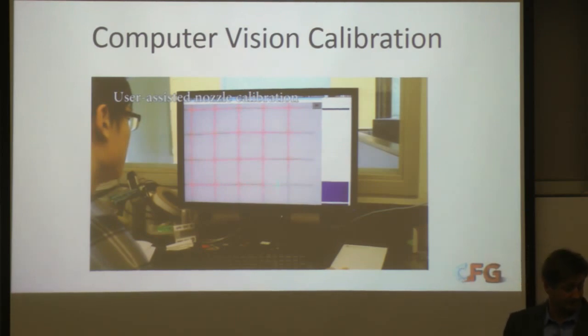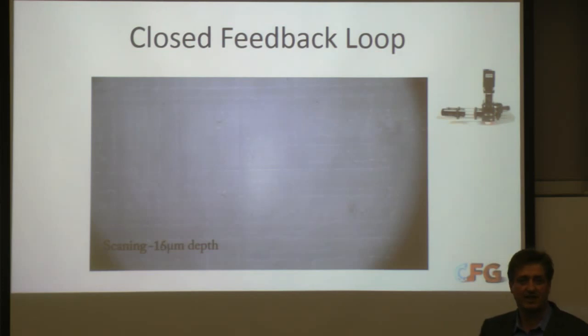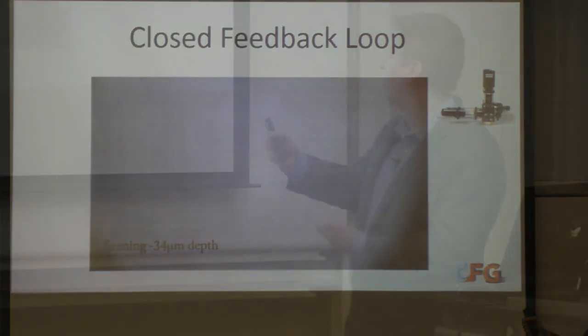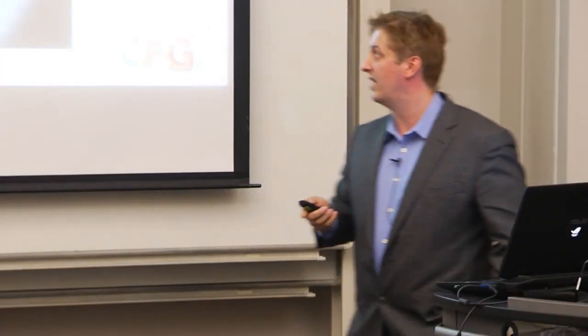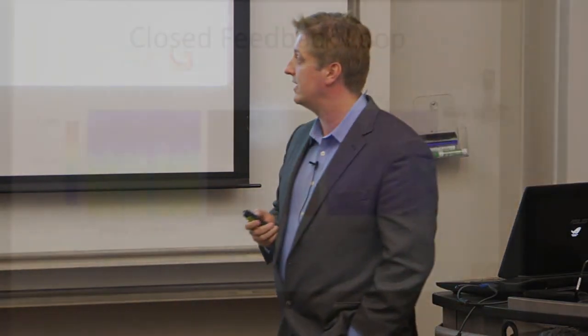Another interesting feature of this system is that we actually have a complete 3D scanner within this loop. It's an interferometry-based scanner that allows you to scan at very, very high resolution. And this enables, of course, quite a lot of different applications. What you are seeing here are the interference patterns that form as you move the platform up and down. From that, you can reconstruct the depth fairly accurately.